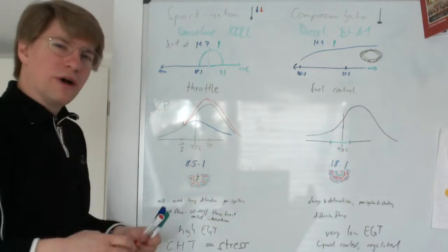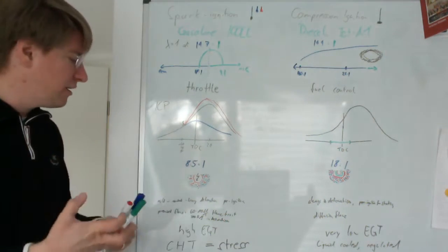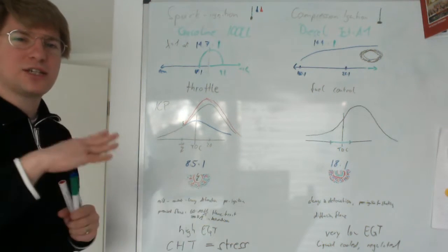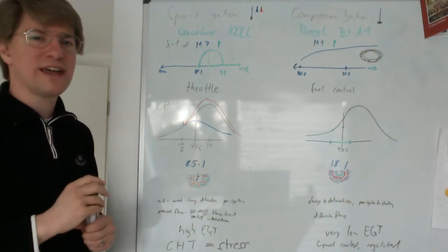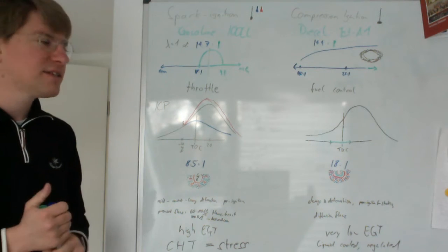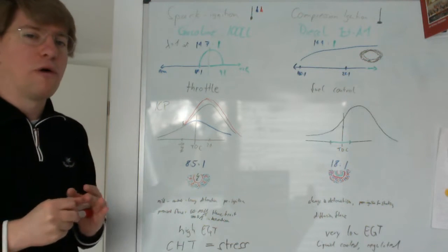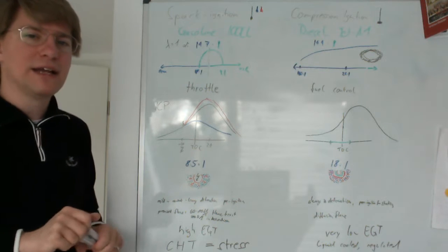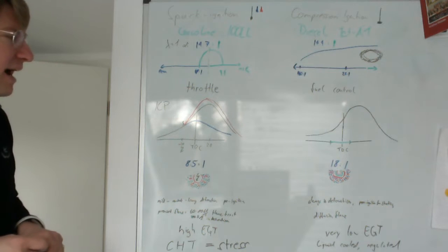So what does that do? It increases the stress on the engine, and we see this in the cockpit with the CHT gauge. If we are running at best power mixture or thereabouts, is about where you will see the highest CHT. That can be fine if we are running at a low, like 65% power setting. Then running there is absolutely fine. But doing this at takeoff power is a really, really bad idea.